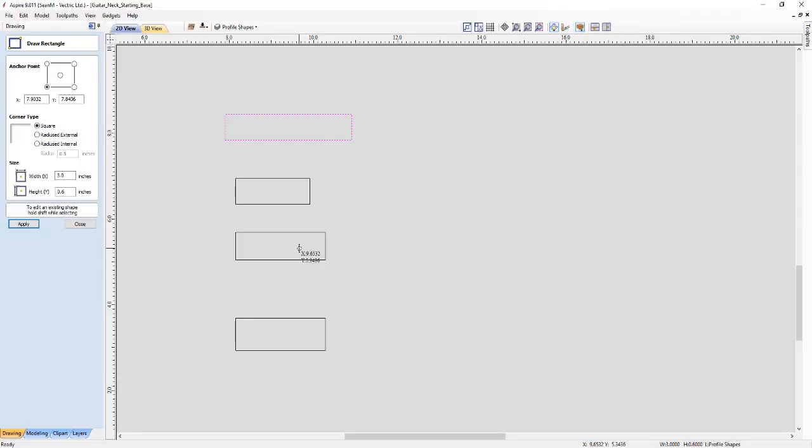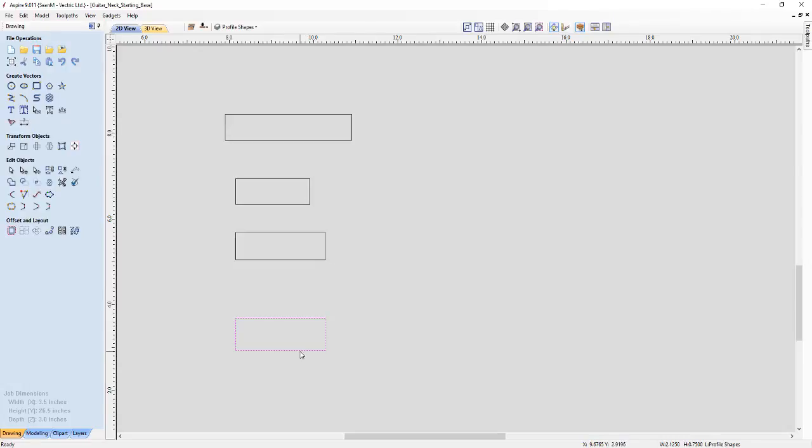So let's go ahead. I'm just going to go into node editing mode so I can start editing these profile shapes. So I'm just going to press N on the keyboard. And close that. I'm just going to delete that rectangle that I just created. Select the first rectangle that we created, press N on the keyboard, and as this is a flat shape, all we need to do is actually just keep the height and the shape as it is, but we just need to delete the actual bottom span. So when we hover our mouse around this bottom span, and we've got the squiggly line next to the actual node editing icon, just simply press the letter D on the keyboard, and that will delete that span for us. And that's all we need to do for our first span.